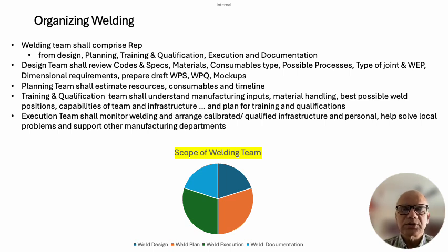properties these consumables are supposed to meet, under what conditions we may have certain additional requirements getting superimposed due to our fabrication, like after 2 or 3 shells are welded, then we are going to have 2 circ seams, and at that stage, or for a dish end when we are going to have a long seam, before we form it, it may have a heat treatment requirement which is not specified by the customer, but that's a good engineering practice which we are incorporating to avoid locked up stresses before we take it for the subsequent operations.